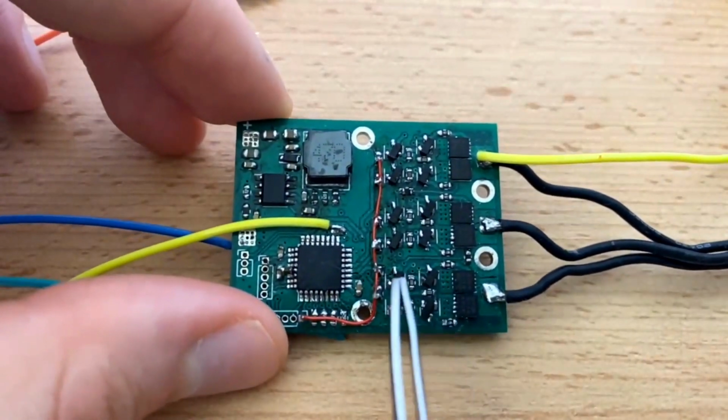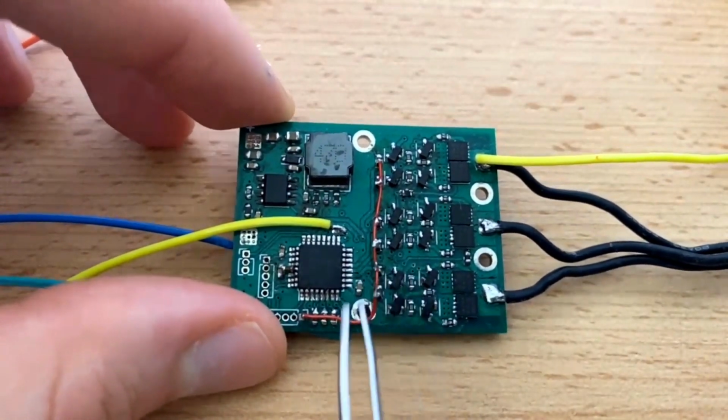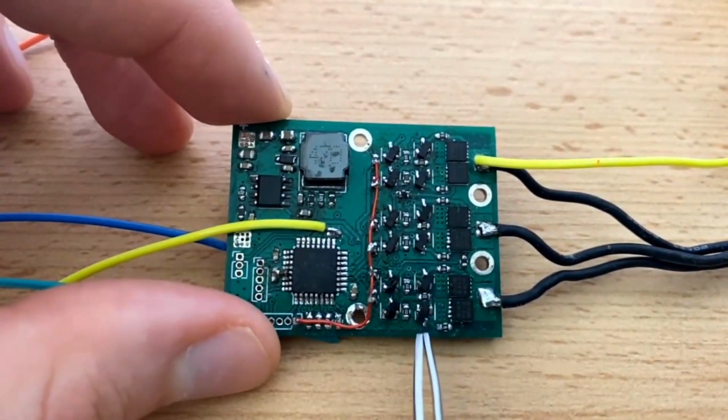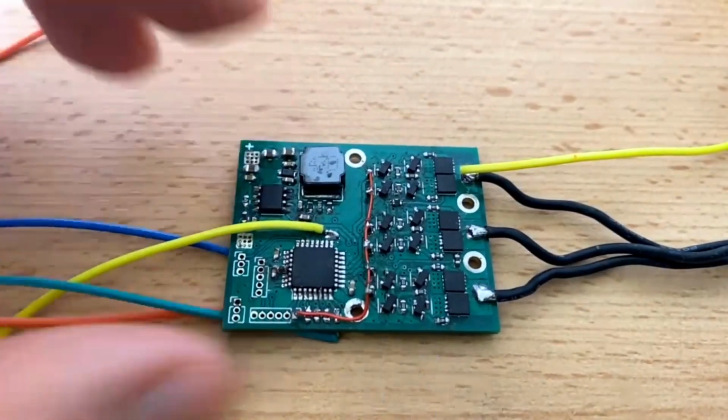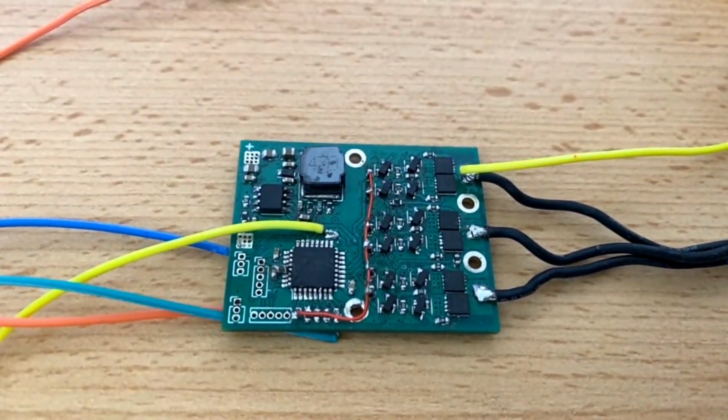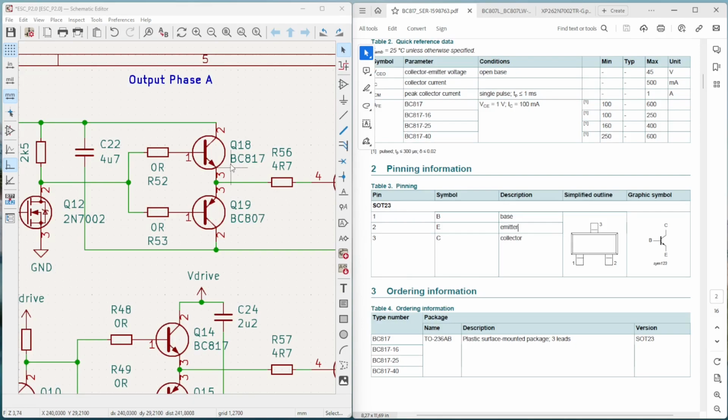In my design here, I used the just discussed gate driver. However, the signal components always broke and the PCB got significantly hot. The reason for this was the selected component in KiCad. I should have selected the component where the base is 1, the emitter 2 and the collector 3. However, I had the collector and emitter reversed.